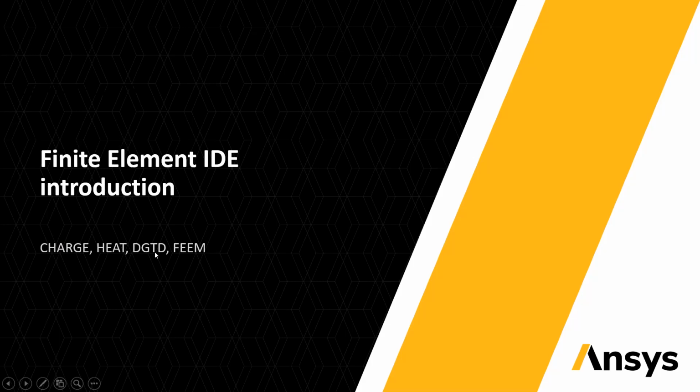DGTD, as I mentioned the other day, uses the discontinuous Galerkin time domain method to solve Maxwell's equations. In essence, it's a solver very similar to FDTD. However, it has its own advantages and disadvantages. But for most applications, FDTD is the right tool to use when you're doing an optical simulation. Given that we have limited time, it's not a big deal if we don't go over DGTD for this workshop. There are examples available online that you can always go to and check out the solver.